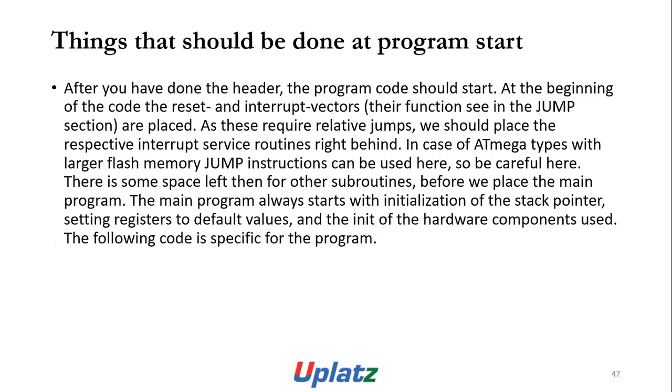Things that should be done at the program start. After you have done the header, the program code should start at the beginning of the code. The reset and interrupt vectors, with their functions, are in the jump section. As these require relative jumps, we should place the respective interrupt service routines right at the beginning. In case of ATMEL types with large flash memory, a jump instruction can be used here, so be careful there. There is some space left then for other subroutines before we place the main program.